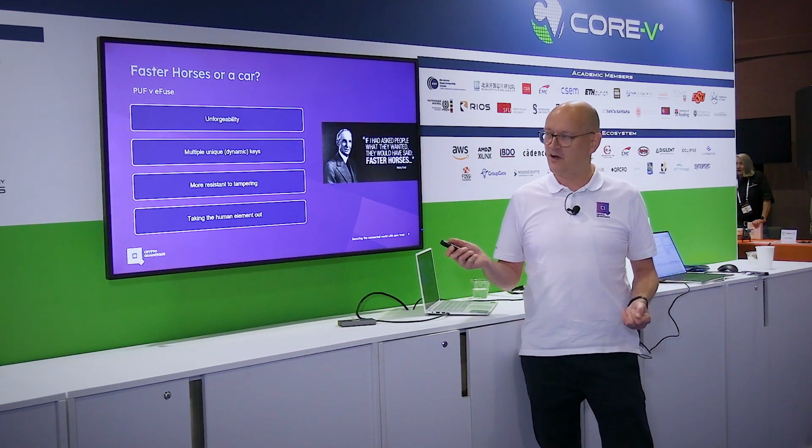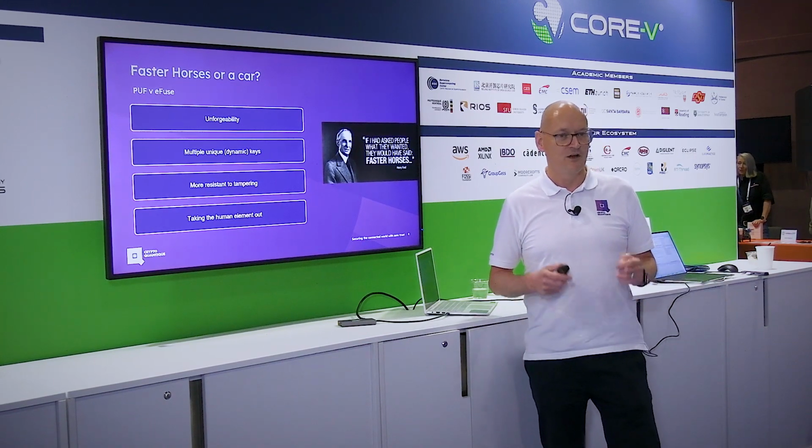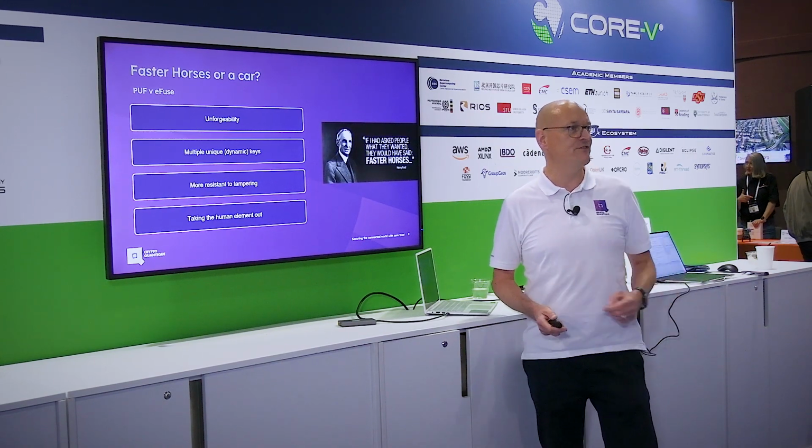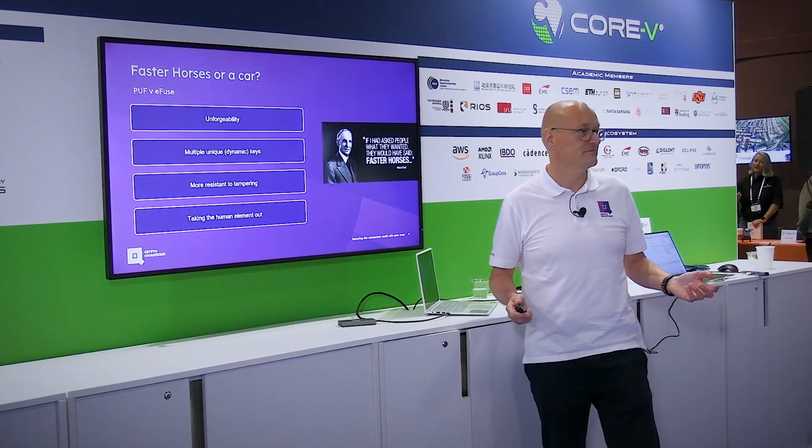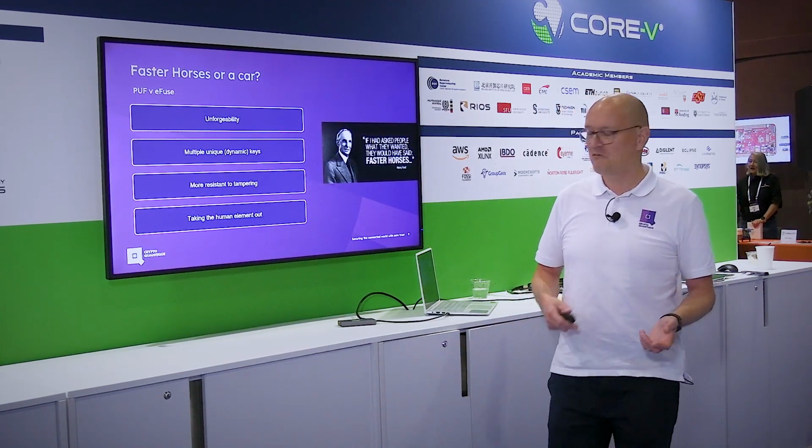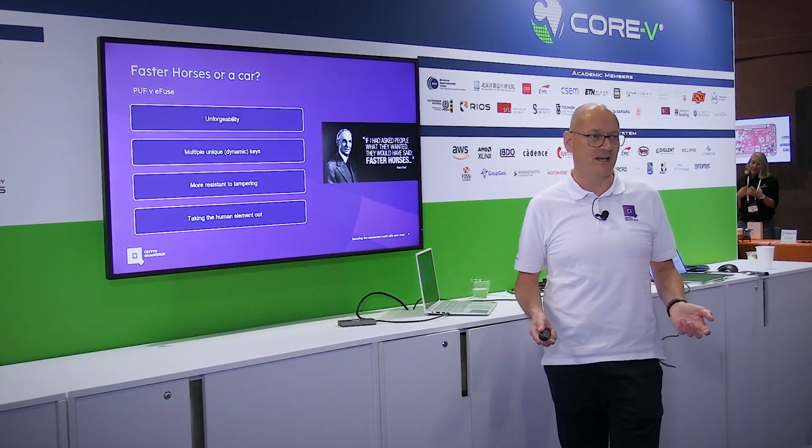Another thing we find customers say, oh, we'll inject keys and we'll blow some e-fuses to lock the bus down. Then no one can get access to it anymore. Well, you can get some rogue software on there that can read the keys. But there's other things. You can't then patch and generate new keys. If your key is compromised, how do you generate new keys? That device is now useless. It's compromised, you can't trust it anymore.